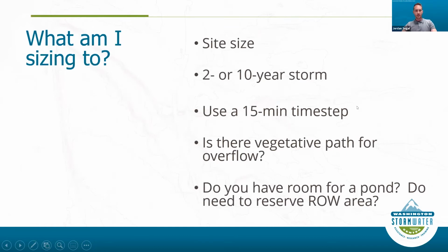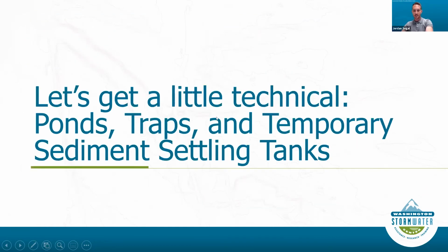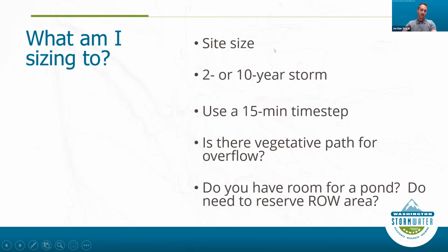Finally, just to get a little technical with sediment tanks, I just want to share a quick example of what you're considering, and you're not just dropping in a rectangle on your AutoCAD. You are sizing a site, and you might think it's completely pervious, but the idea is it's compacted, it's eroded, and so you need to consider that it's not just this completely fully infiltrative site, that it's not pervious. We have sizing criteria within the manual, within the code for the city specifically, and maybe that might be the case for your city or county as well.